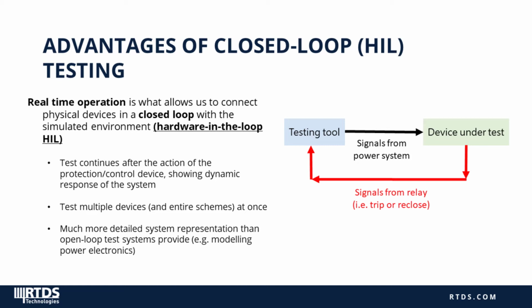Traditionally, hardware-in-the-loop testing has been done with protection and control equipment, but more recently, the concept of connecting power equipment like renewable energy hardware, converters, motors, and loads to the simulator in a closed loop has emerged as a popular application. And that is referred to as power hardware in the loop testing, or PHIL testing, and that's what we're discussing today.